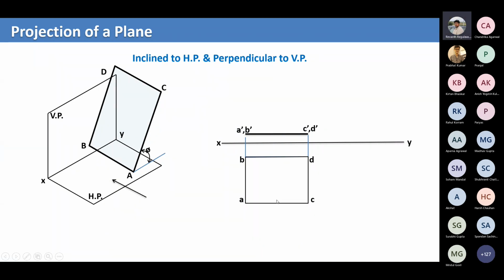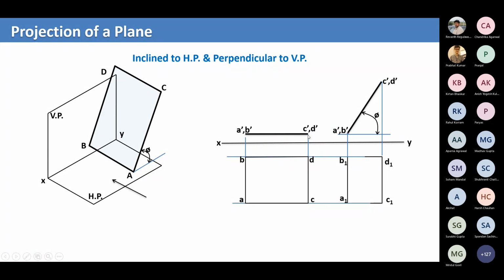Yeah, ABCD, and then it is a straight line in another projection. And now we draw the construction lines parallel to XY here also. And then this is the orientation of the plane at an angle phi. Now we draw the construction lines from vertical construction lines, and then we find the intersection points, and then we label them. So everyone understands how these are labeled, right?